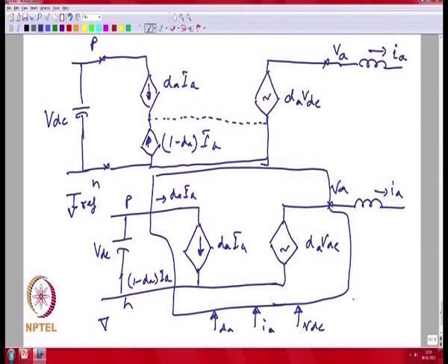Also, the assumption that we have made in this model is that the duty cycle belongs to the range 0, 1. If your duty cycle goes out of the range, you might find that your energy conservation equations may not be satisfied; your amplifier cannot generate more voltage than what is available. So, you need to ensure that you are respecting your duty cycle constraints.